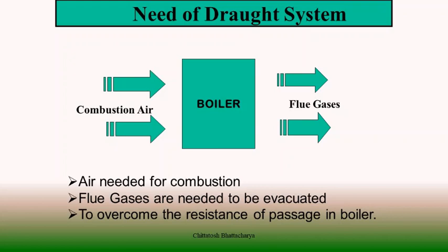In the boiler, we are required to supply combustion air, which comes in different forms, either primary or secondary air, to supply oxygen for the combustion. As a result of combustion we get the product of combustion, and out of this, ashes are collected in various phases, either in the bottom of the furnace, in different heat trapping zones, or outside the furnace and boiler. We have a dust separating and collection system, and the cleaned flue gas is disposed through the chimney and evacuated by the induced draft fan.